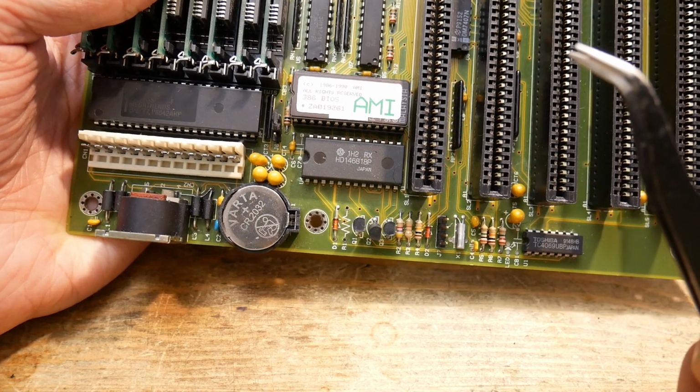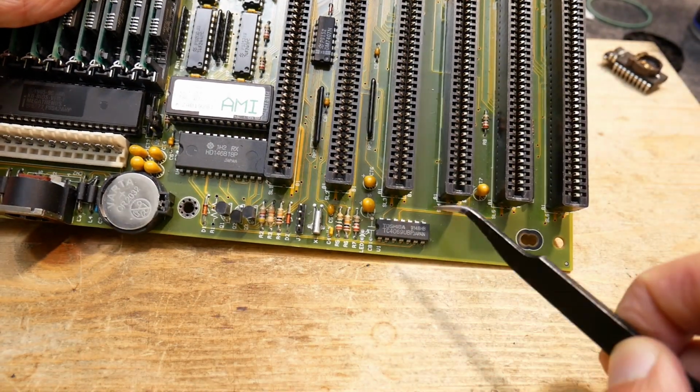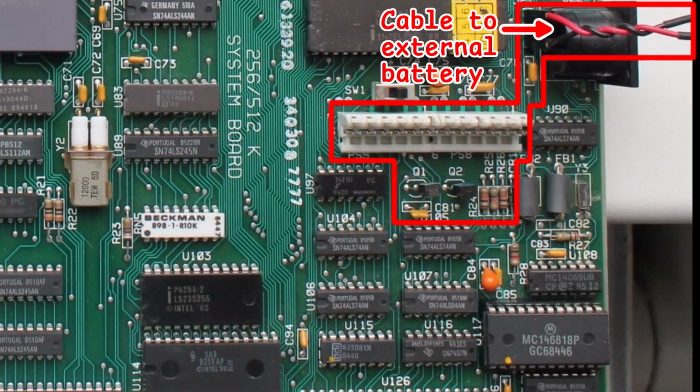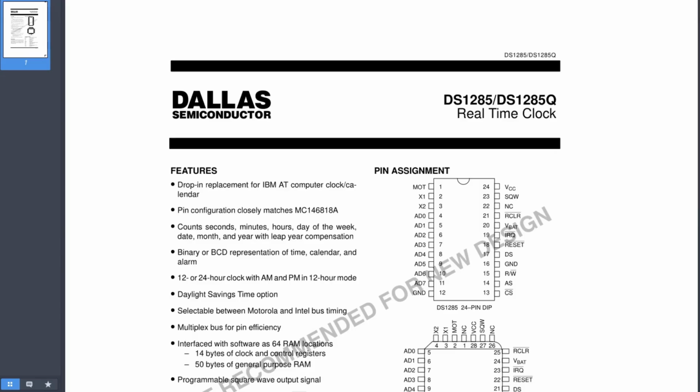However, as we all know, the industry is always searching for ways to reduce costs, and so some work has been done to reduce the number of external components required to implement this. First of all, the power circuit, which contains quite a lot of standalone parts to control the switch between the battery and the main power supply to avoid battery drain when the PC is turned on. So a new RTC IC was introduced which closely matched the functionality and the pinout of the previously used Motorola MC146818, but brought some additional functionality. Dallas DS1287 was one of the names of the new chip.